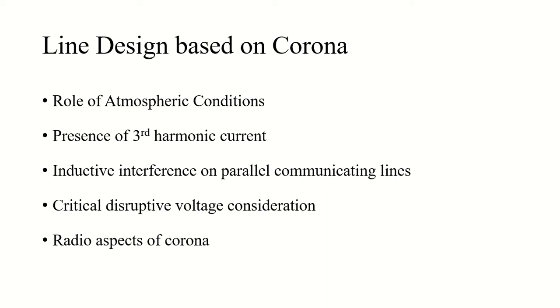So you have to eliminate this third harmonic component, so that this harmonic component does not induce inductive interference on my communicating circuits and parallel communication lines. So the design engineer must take care about this inductive interference and non-sinusoidal corona currents as well.